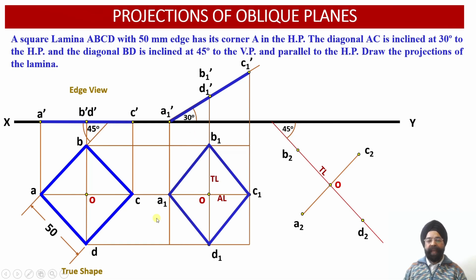So this way we have been able to rotate this figure, the plan projection view which we had drawn earlier, to an angle of orientation of 45 degree with respect to the vertical plane, such that the true length diagonal BD, that is B2 D2, is lying at an angle of 45 degree with respect to the vertical plane. So having obtained the plan projections corresponding to this oblique lamina A2, B2, C2 and D2, now the corresponding points will be located in the elevation view as well.